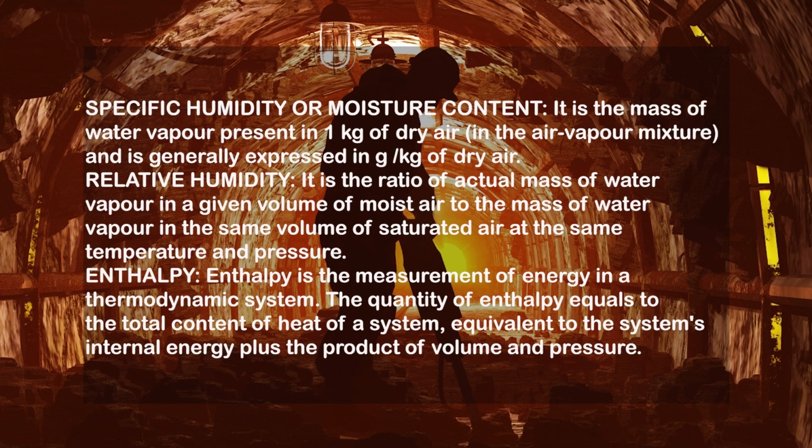Now come to relative humidity. Relative humidity is the ratio of the actual mass of water vapor in a given volume of moist air to the mass of water vapor in the same volume of saturated air at the same temperature and pressure. It is basically a ratio, and it is expressed in percentage.